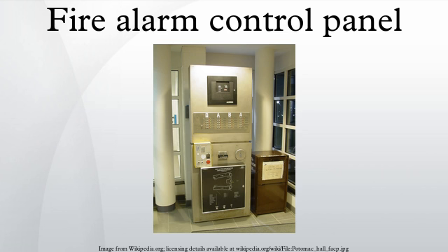Relays are used to control a variety of functions such as switching fans on or off, closing or opening doors, activating fire suppression systems, activating notification appliances, shutting down industrial equipment, recalling elevators to a safe exit floor, activating another fire alarm panel or communicator. Mapping, also known as cause and effect, or programming. Mapping is the process of activating outputs depending on which inputs have been activated. Traditionally, when an input device is activated, a certain output device is activated.